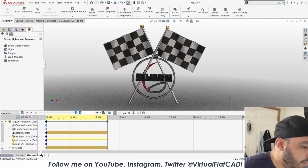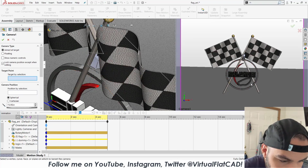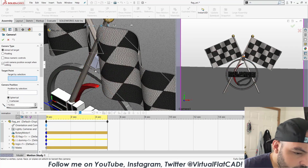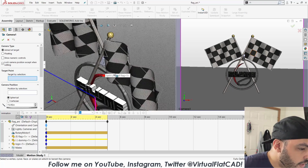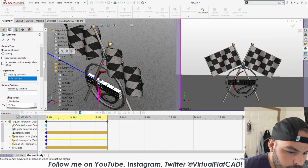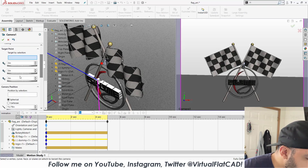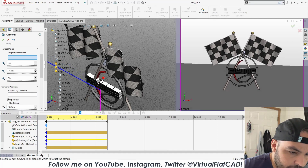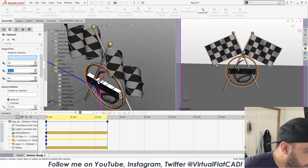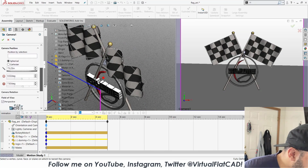We're also going to create a camera, so we can right click, add camera. Okay, so the view is right here, target by selection. So that's where the camera is pointing to. I'm going to try the origin. No, it has to be a little bit less than that. I'm going to show numeric controls. And we want it to look down on the Y, so I'm going to just turn that down until the preview looks correct. Camera position is pretty good for right now.